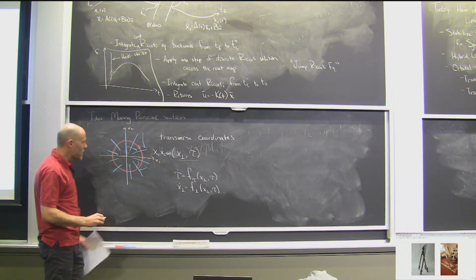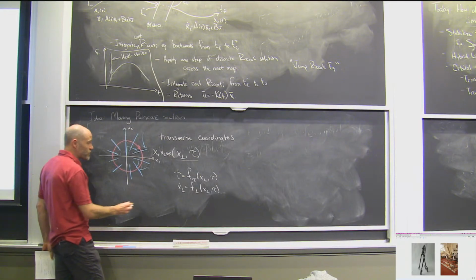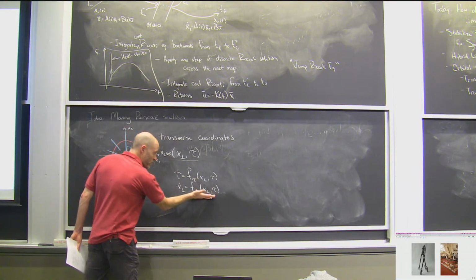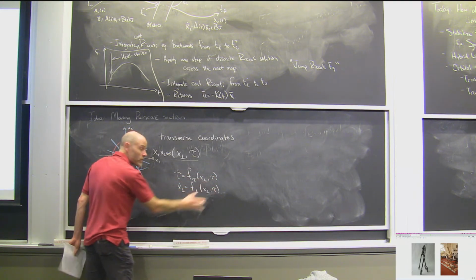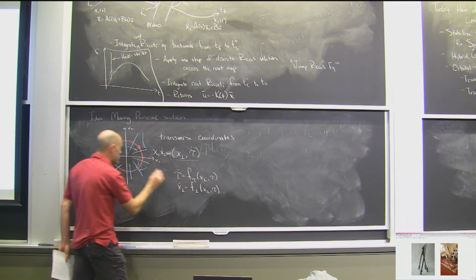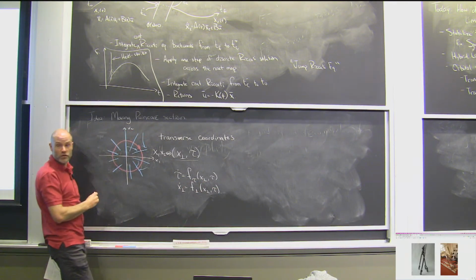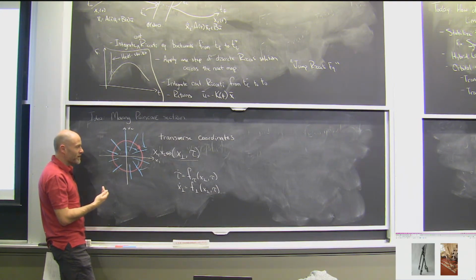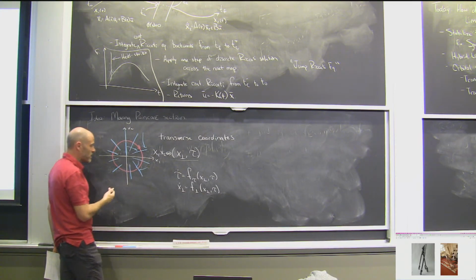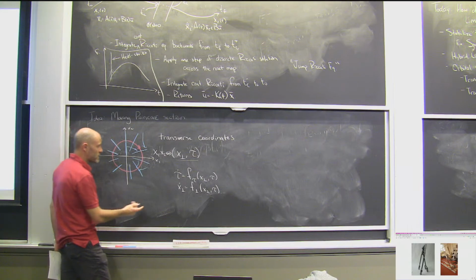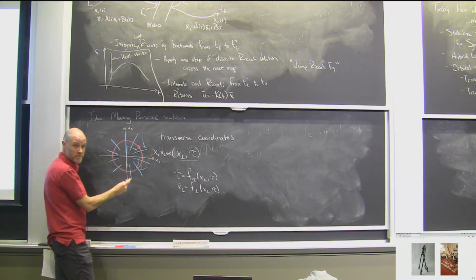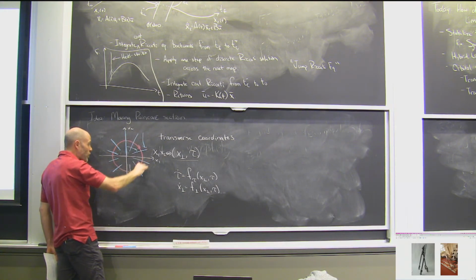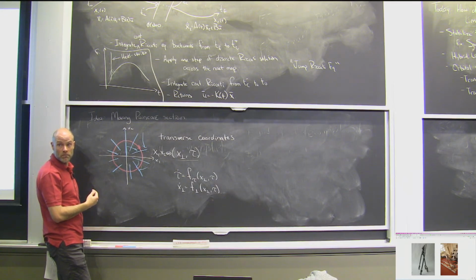It turns out that if I can establish stability of just the transverse coordinates and put minimal or no assumptions on the rest, then that gives me the ability to talk about orbital stability of that periodic solution. It makes sense, right? But it needs to be established that you can write a Lyapunov theorem, for instance, that says that if I just show that the blue directions are stable, in some sense, that implies orbital stability of the red trajectory.